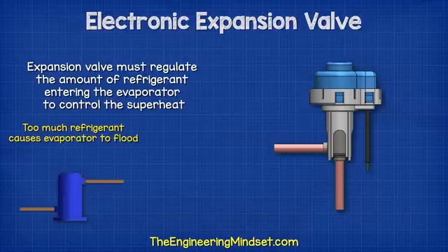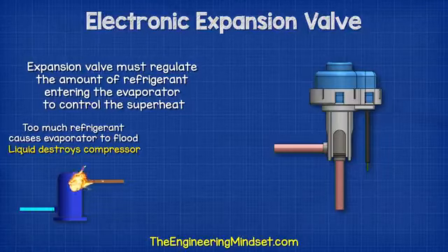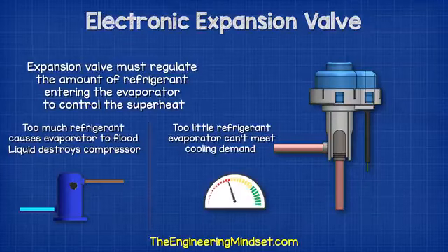If it allows too much refrigerant to flow, it can flood the evaporator, so the refrigerant doesn't evaporate and liquid reaches the compressor and possibly destroys it. But if it lets in too little refrigerant, the system won't provide enough cooling, and so it operates inefficiently.